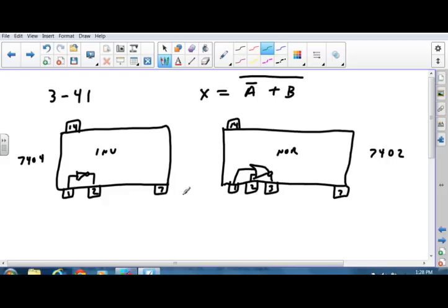And then there's a pin 7, and here's pin 14. Okay, so now we're going to change colors. We're going to ground pin 7 on both of them, because if we don't, it's not going to work. We're going to add power, 5 volts, to pin 14 on both the chips, because if we don't, it's not going to work.